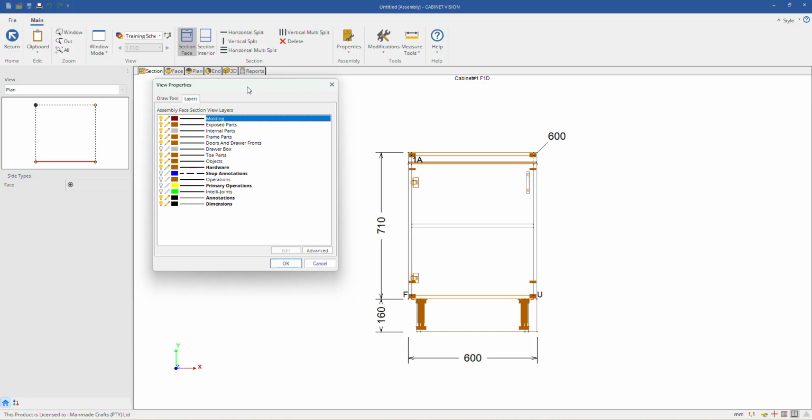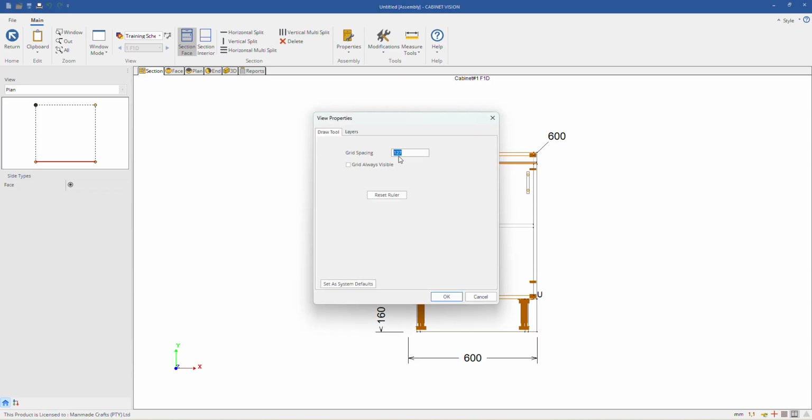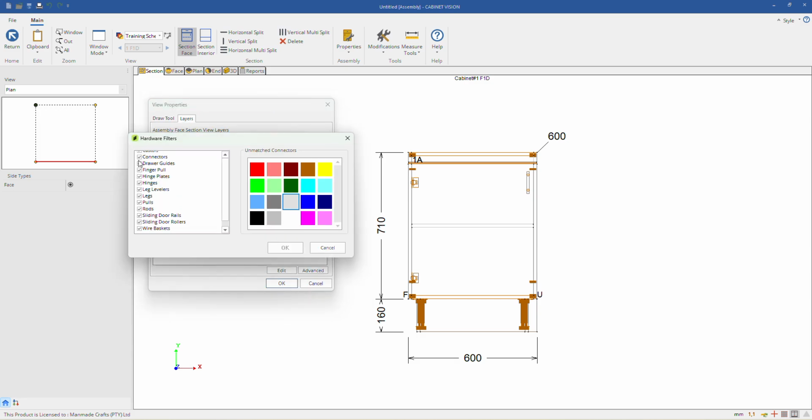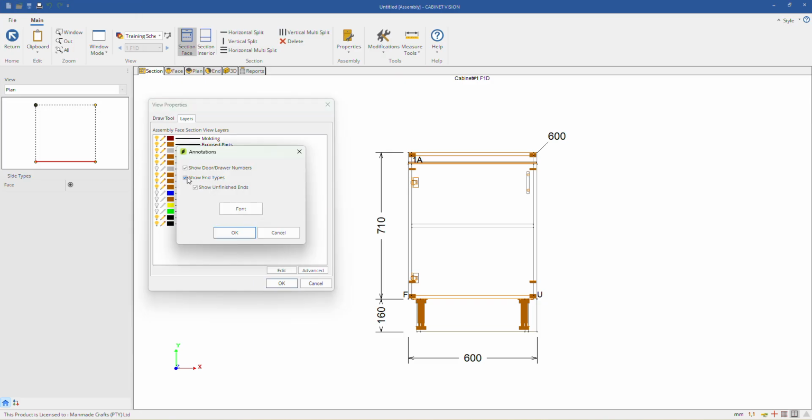But also, the main thing with this is, if ever you're in a view and it's not showing something that you're sure it should, layers. That's where you always go and check first. Right. Right click, properties, go through all of the layer options quickly, check what looks off or what might be hidden, and then just go and modify the look. For instance, on my annotations. Mm-hmm.